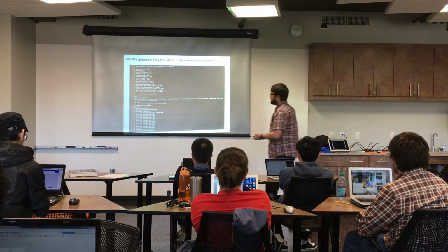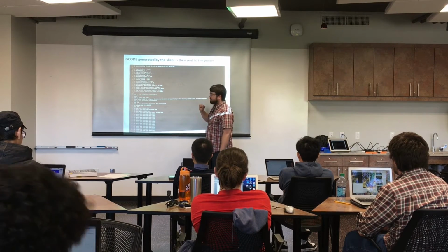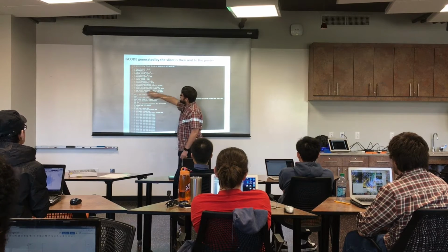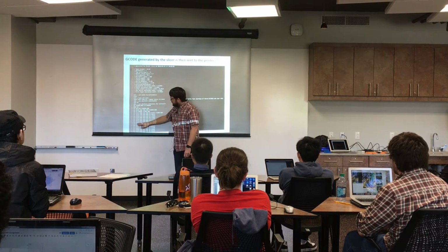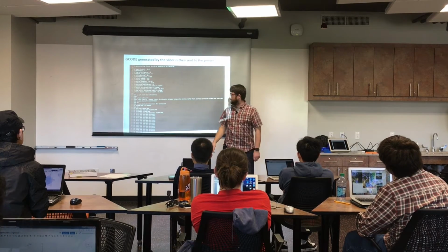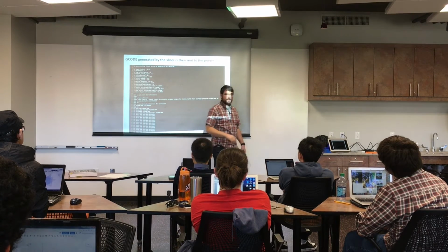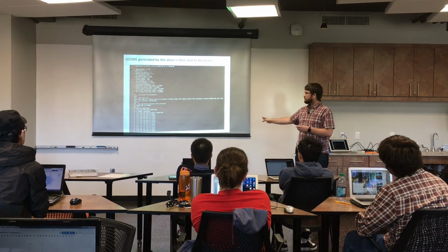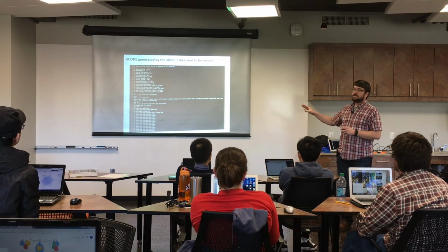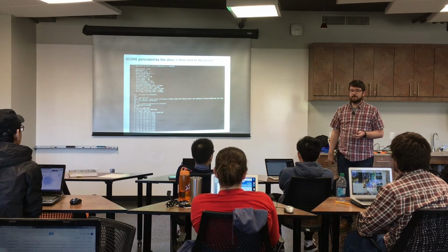And then the slicer puts out the G-code. This is some G-code for, I think it was a DC-DT bracket or something like that. But you can see I generated it a couple years ago. And these are all comments. And then it's just all of these instructions. Move to X, Y, and extruder coordinates. Move to X, Y, and extruder coordinates. Here it's moving to a certain Z coordinate or a certain height. And these files, they're just plain text. And they can be, you know, like 20, 25, 50 megs for a relatively large part because it's telling the printer everywhere it needs to go.